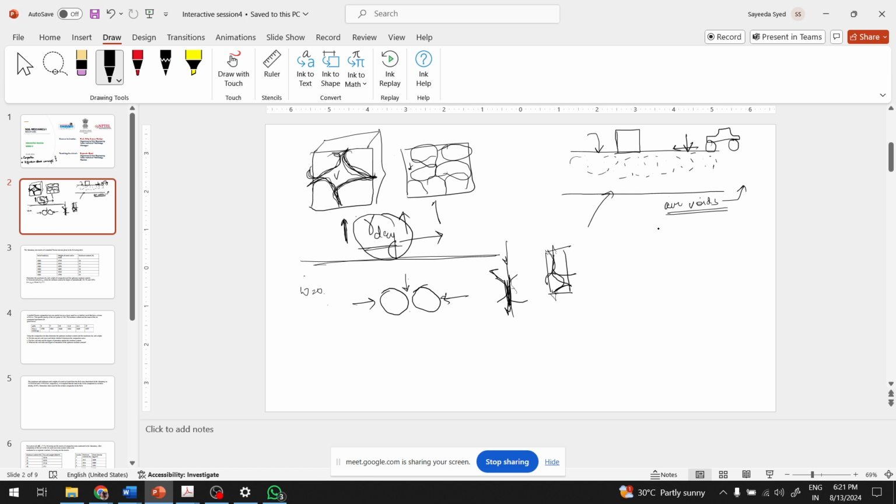because after some time more and more water will mean that more and more voids are present, isn't it? So when the water starts replacing the solid particles from the unit weight, then the unit weight will again decrease. That is why when you draw the compaction curve, gamma d versus w, you see that with increasing water content, the gamma d increases up to a certain point and then it decreases again.